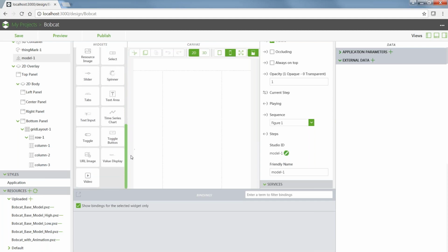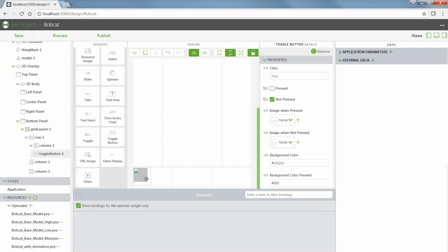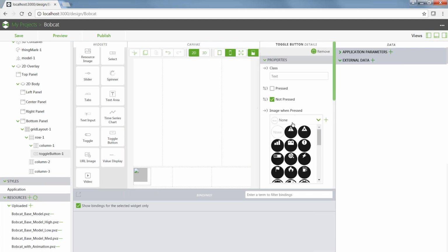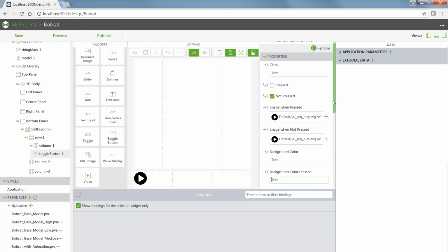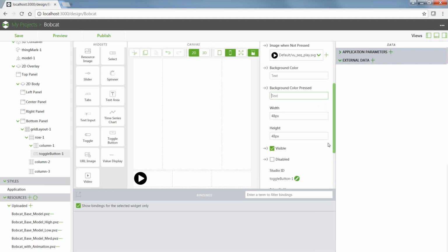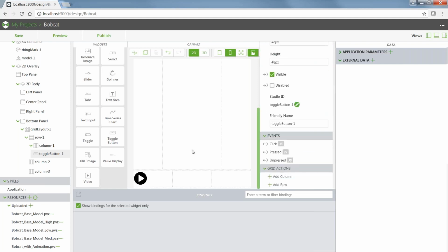There's a multitude of different ways that you can trigger the sequence within a model itself. So if you want to use like a click of the model, you want to use a button, anything like that. We're going to go ahead and use a toggle button for this scenario today. And there's a lot of images cooked into Vuforia Studio here to actually give your button some style. You're not married to these images, so you can go ahead and create your own via, like, Photoshop or anything, any common convention like that.